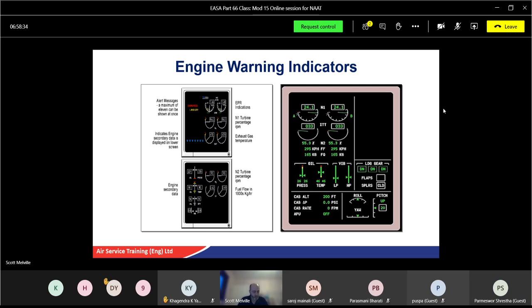Okay. At what percentage RPM during a start cycle will the APU de-energize the starter circuit? 95%. Not before that one. 35. 45. Yeah, 35%. Good. All right. What valve will open at approximately 10% RPM? Solenoid, fuel solenoid valve. Yeah, fuel solenoid.